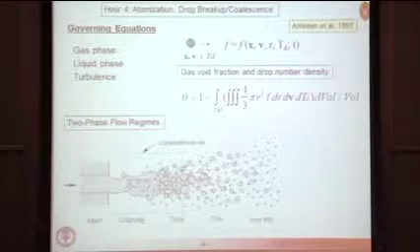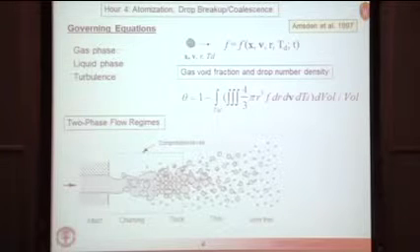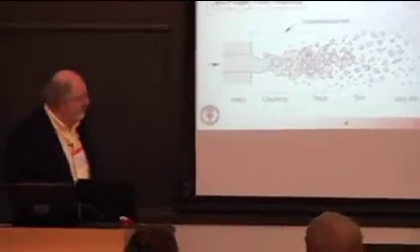And we'll see moments of this distribution function appear when we start looking at source terms in the governing equations. The fact of the matter, though, is that current spray models assume that the droplets occupy negligible volume. So you can see that even in this case, most of the cell consists of gas. There is liquid here, but we are saying that the liquid volume is negligible. And that's certainly true as we move further away from the injector. It becomes a questionable assumption, obviously, closer to the injector. But basically, this is the big assumption that most spray models make.